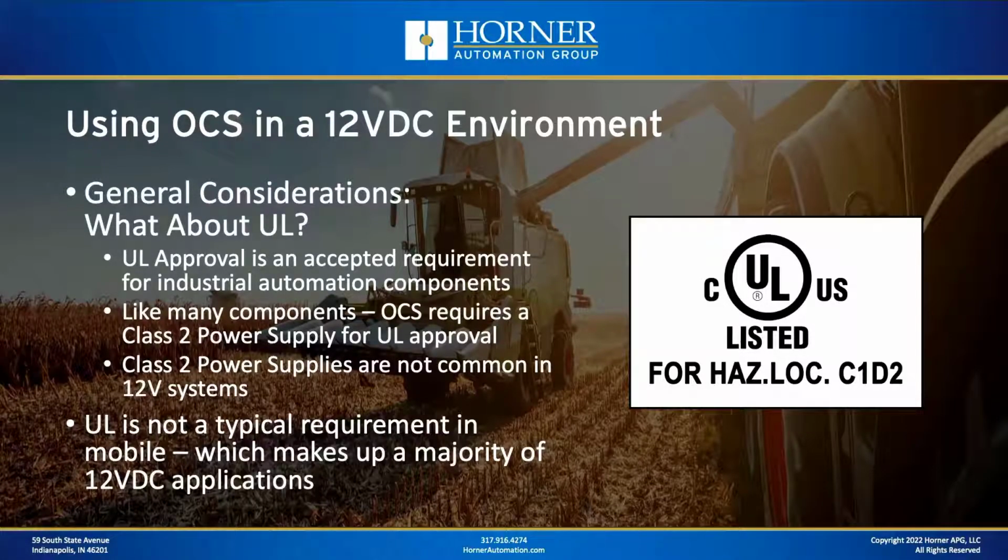That is, it requires a Class 2 power supply to be used for UL approval. Now, what is a Class 2 power supply? Well, basically, it's a power supply whose energy is limited to limit some of the situations that can cause problems. And I believe the limit is about 92 watts total.